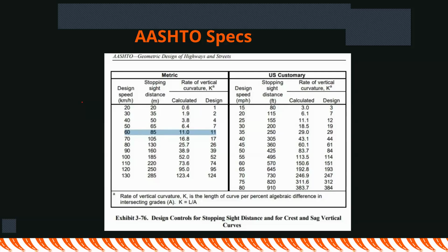If the sight distance is greater than 160, it means if you see an obstacle within that curve, you will need a distance greater than the length of the curve to see. Therefore, the driver cannot safely bring that vehicle to a stop within the curve.